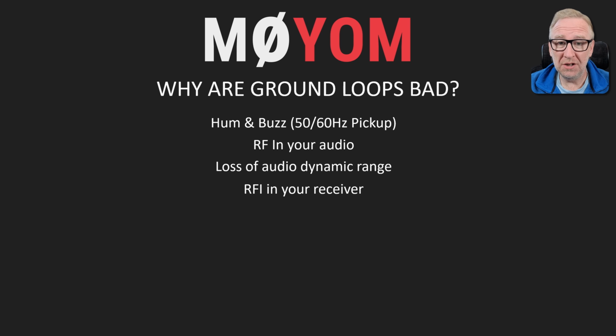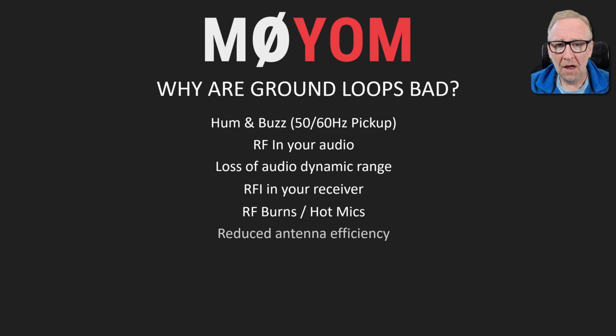They can cause RFI in your receiver. If you're QRO, especially if you're running an amplifier, they can cause RF to get into your devices to such an extent that the current flow on the cables, chassis, or microphones can lead to shocks, which is not a good thing. I've experienced this myself, and it's not pleasant to get an RF burn off of the chassis of a piece of equipment. They can lead to reduced antenna efficiency.